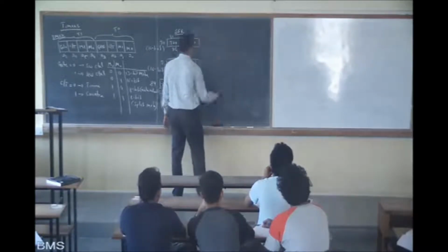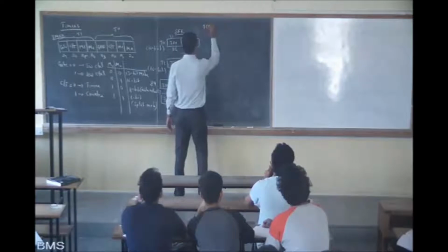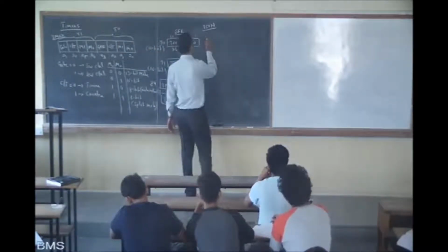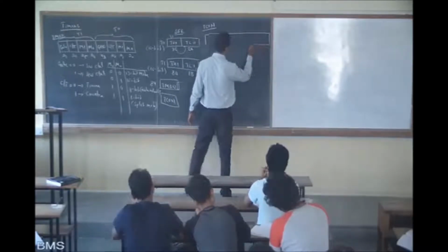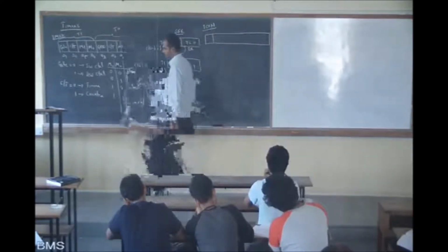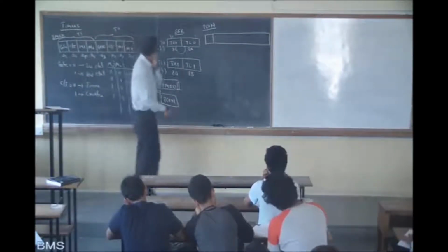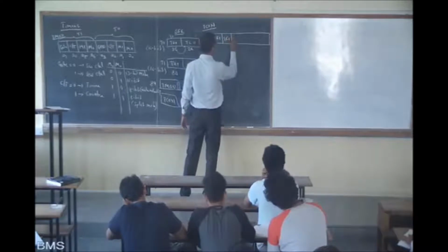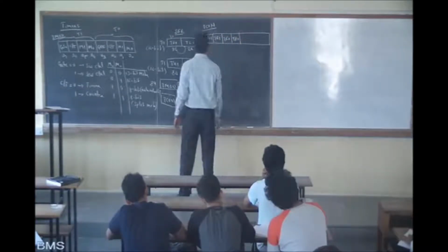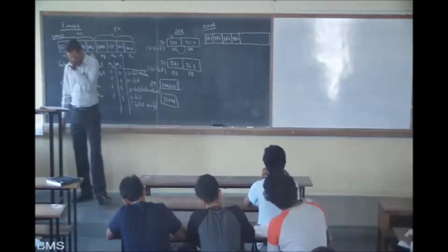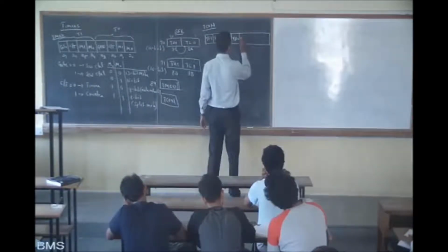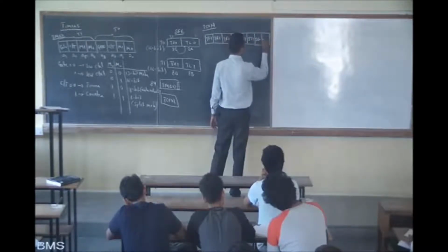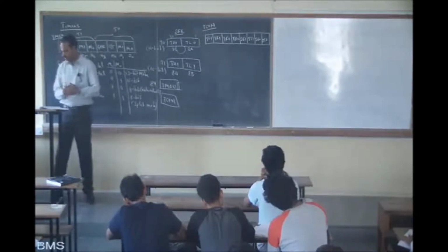Now the TCON register. We have discussed TMOD, and this is TCON. What is TCON? TCON is again an 8-bit register which has the following bits: TF1, TR1, TF0, TR0, IE1, IT1, IE0, IT0.